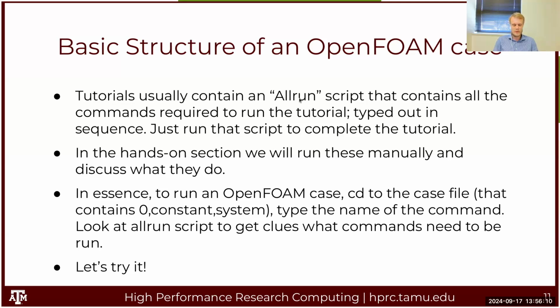So in essence, to run an OpenFOAM case, we change our working directory to a case folder. That's the folder that contains the zero, constant, and system subfolders. Then we type the name of a command. We can look at the all-run script to get clues what commands need to be run for this particular tutorial. And when you run those commands, OpenFOAM will read all the settings files in the system, constant, and zero folders, and it will run. So that concludes the intro.